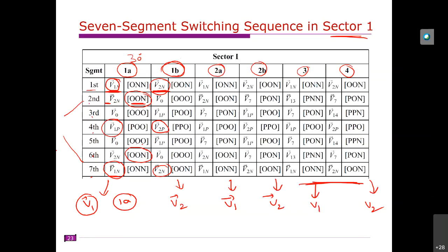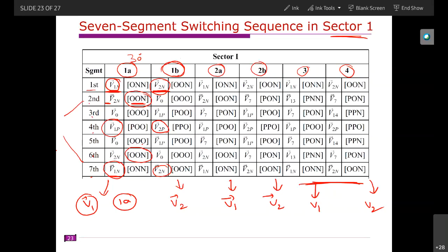So this is how the switching sequence is generated, with reducing the neutral point voltage. However, with the space vector modulation technique, we cannot completely balance these two capacitor voltages or these two DC sources, right?